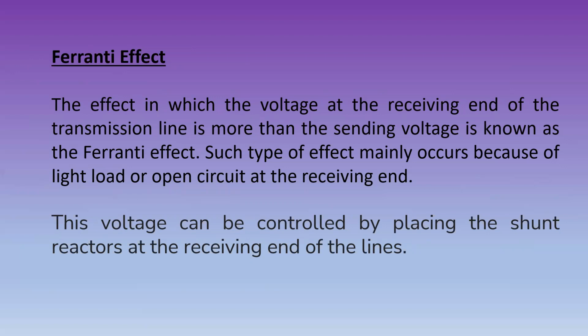Such an effect mainly occurs because of light load or open circuit at the receiving end. At the receiving end, if we do not have any load or if the circuit is open, then the receiving voltage will be very high. And as we know, it will happen in long transmission lines, due to the capacitance in the cable.